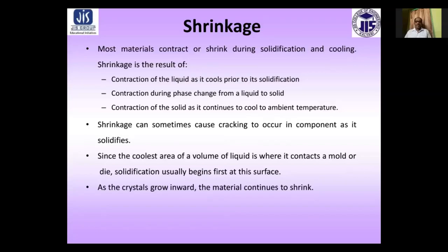Shrinkage can sometimes cause cracking to occur in a component as it solidifies. Since the coolest area of a volume of liquid is where it contacts a mold or die, solidification usually begins first at these surfaces.